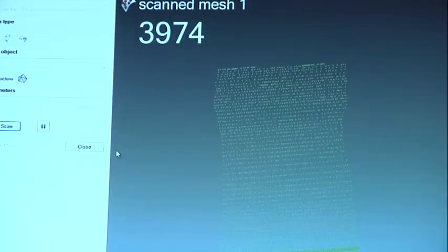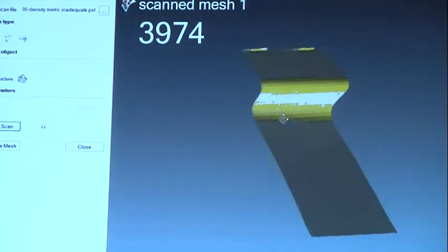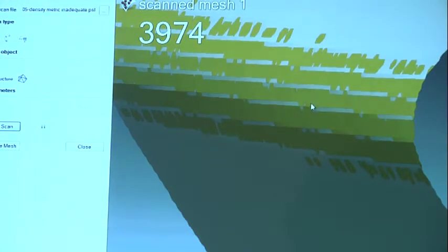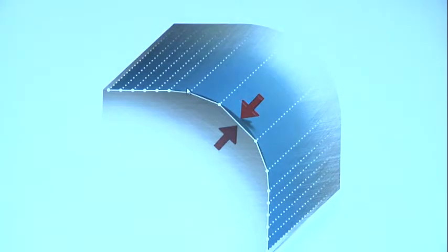Let's see what happened when we scan it. The area is highlighted in yellow. If we look at this closely, you see there's kind of a tessellated surface, where we have flat surfaces in this area. So how we highlight those areas is we fit some kind of a small surface there, and we look at the deviation between that smooth surface and the connection between the points or the laser line. If that distance is bigger than a threshold, that's where we flag this as a quality error.